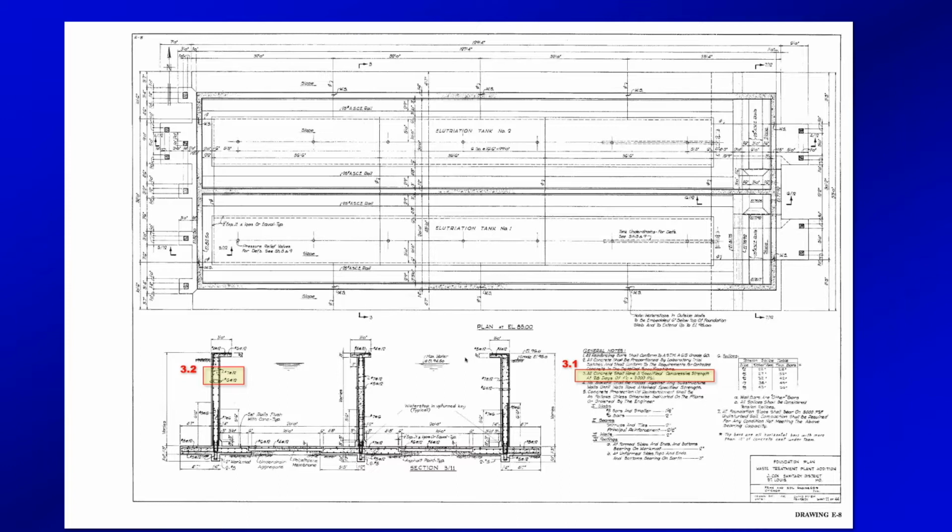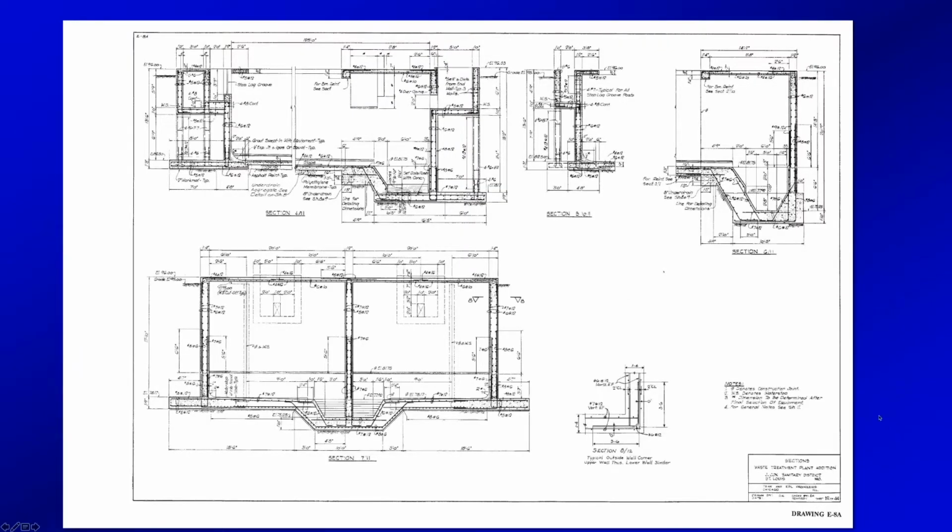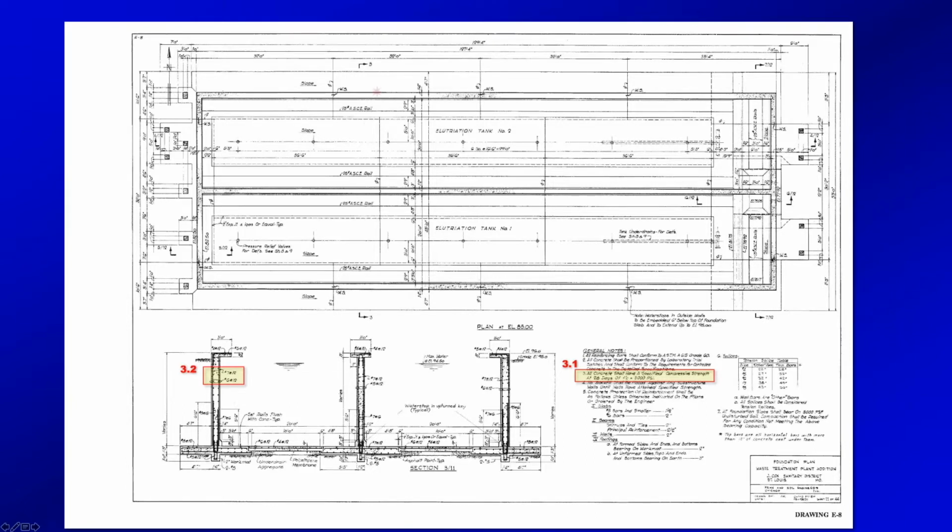Oh, well, it's the only answer that could be. They didn't ask you what the tie bars are or the hook bars are, all this stuff coming up. See all these bars that you see down in the footing, they're coming across and then they're angling up. So those are really footing reinforcing. It's not wall reinforcing. They're just tie bars. So if you look at the plan above, there's the plan. Let me go back. These are the outside walls as you go around it. It's the only thing it can be.